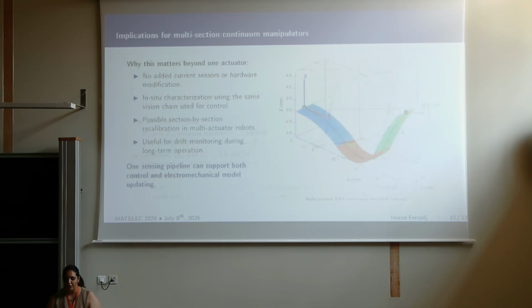So this method allows us to estimate the hysteresis loop just by looking at the actuation from a macro scale level, for us who work on robotic systems. And now it is easier, for a more complex structure, to define the hysteresis loop without needing current measurements.